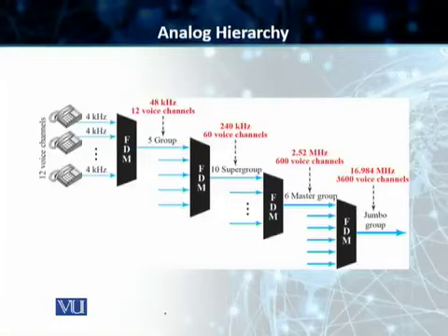So students, using multiplexing and specifically using frequency division multiplexing, we have got an analog hierarchy in which we take signals from lower bandwidth lines. As you can see on the right hand side, we have got 12 4 kilohertz signals combined together. Yaad kijega, a telephone line analog signal, voice signal, has got a bandwidth of 4 kilohertz. So what we have done is, we have taken 12 voice channels. Each of the channels is carrying an individual 4 kilohertz signal. And we have multiplexed that to start with onto a higher bandwidth line to create something that we call a group.